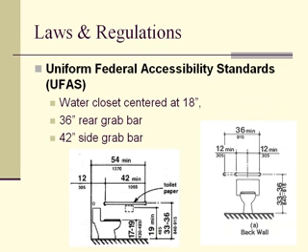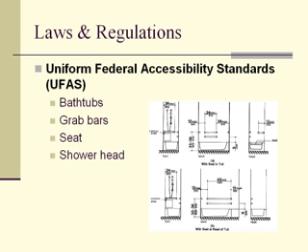These water closets require clear floor space, just like the other elements, like when we mentioned that a person on a stationary wheelchair required that 30 by 48 inch. So the clear floor space for water closets is usually 60 inches wide, depending on whether it is floor mounted or wall mounted. If it is wall mounted, it can be 56 inches. If it is floor mounted, it has to be 59 inches. So there are certain specific space requirements for these. Generally, when you are in the bathrooms, by providing the 60-inch turning space, these clear floor space requirements will be met. So I'm not going to go into too much detail on those.